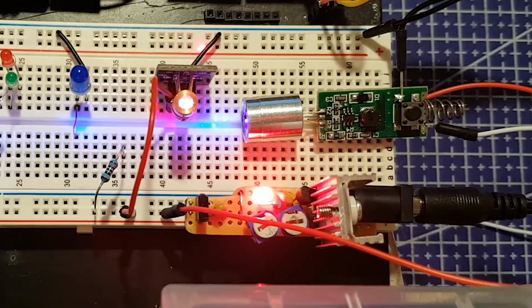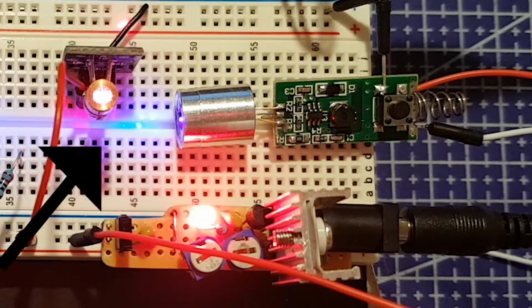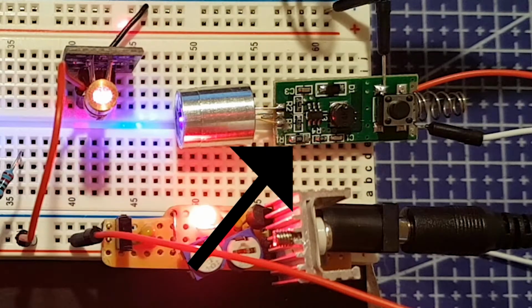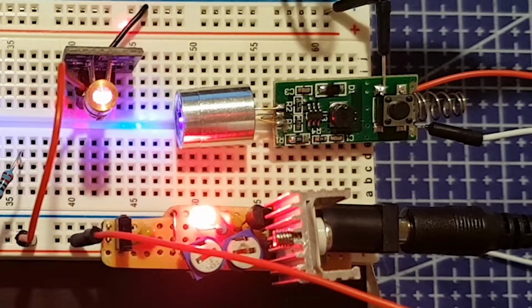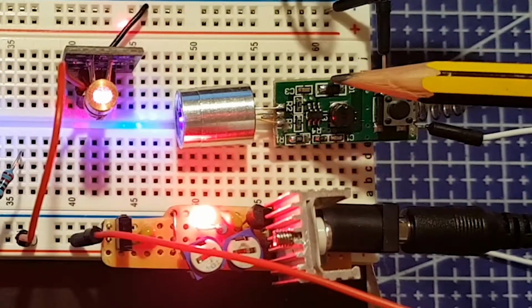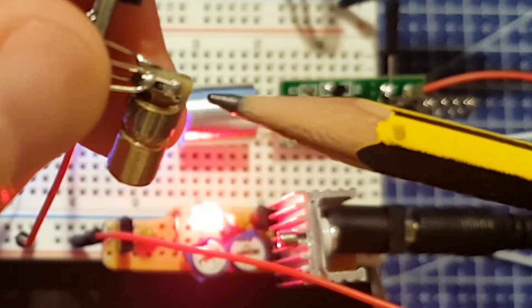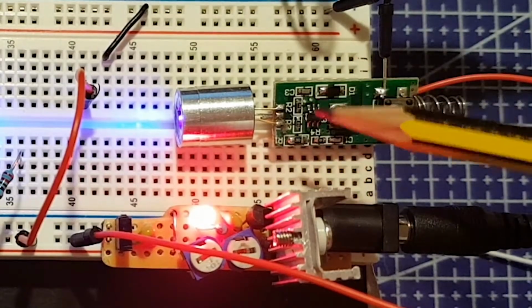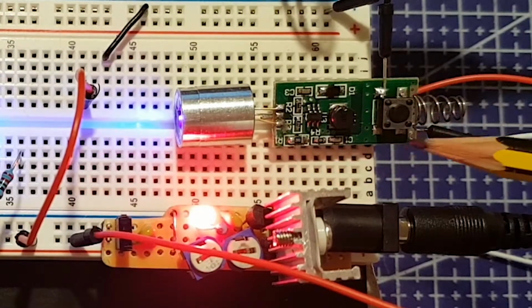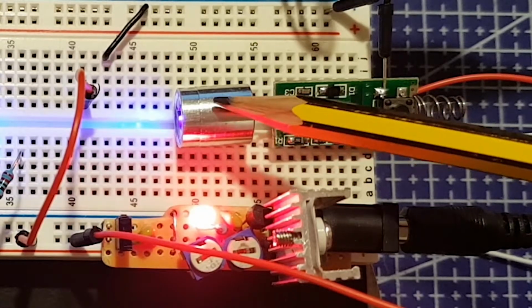Laser diodes have rather sensitive current requirements similar to the LEDs, so have to be used in conjunction with a driver circuit. This will provide a constant current to the laser diode whilst also limiting the maximum voltage that can be reached. This is how these particular lasers are being powered right now. It's a very, very small circuit and it's right inside there. And this one here comes out of a laser pen, so the circuit board is a little bit bigger, but it's actually still attached to the laser diode, which is this section here.